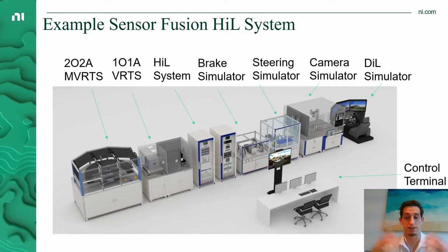And one thing that it scales into is if you had the requirement to test all of the ECUs in a distributed system, it would be an entire room of testers. And we've seen this actually deployed at customer sites: they do an injection system for their ECU, they do an over-the-air system for their radar, they do an over-the-air system for their camera ECU, and so on down the line. And it creates this massive block of different types of simulation platforms and different types of integrations for hardware in the loop to do all this.